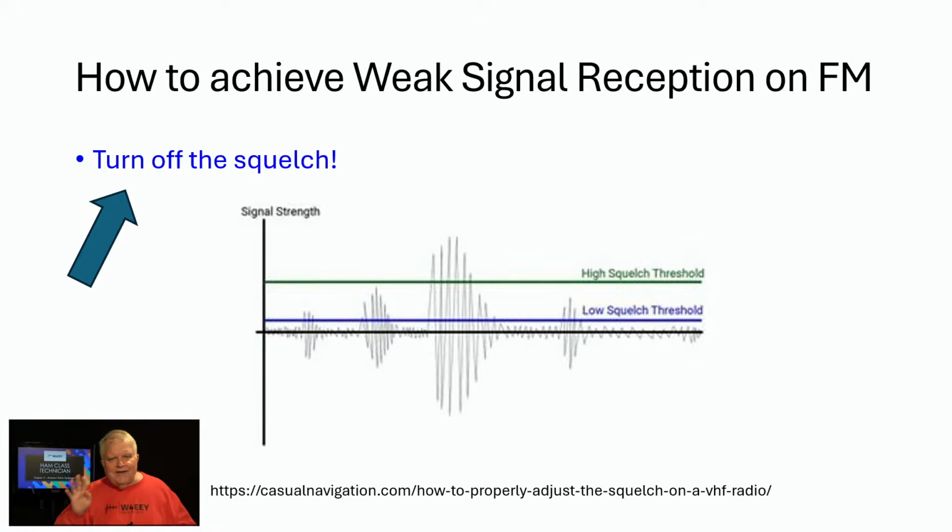That way you can hear him in the noise. Because if you have the squelch on, he may never break your squelch, and you may never hear him whatsoever. So for weak signal reception on FM, you need to turn the squelch off.